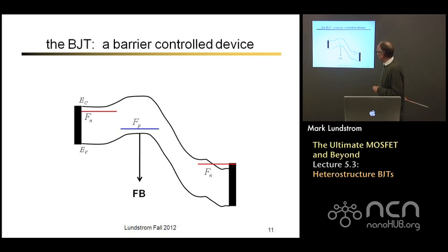So the forward bias on the base lowers the barrier between the emitter and the base. What the ohmic contact does is it attaches to the majority carrier quasi-Fermi level in the base, that's F sub P for holes, and pulls it down. If the emitter was grounded, the quasi-Fermi level for electrons stays where it was in equilibrium, and now we've separated them by the base emitter voltage.